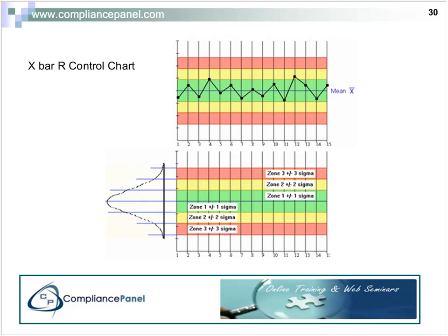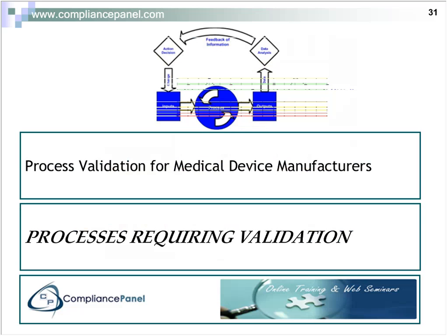And then the green distribution would include the red, yellow, and green from our previous drawing of the normal distributions. So at any rate, we want to have a tightly centered distribution, and we can have some variability over time in our production process, but we want the settings to stay inside that green area. So those are all statistical tools we can use in doing the process validation and then following the process validation to keep our process in control.